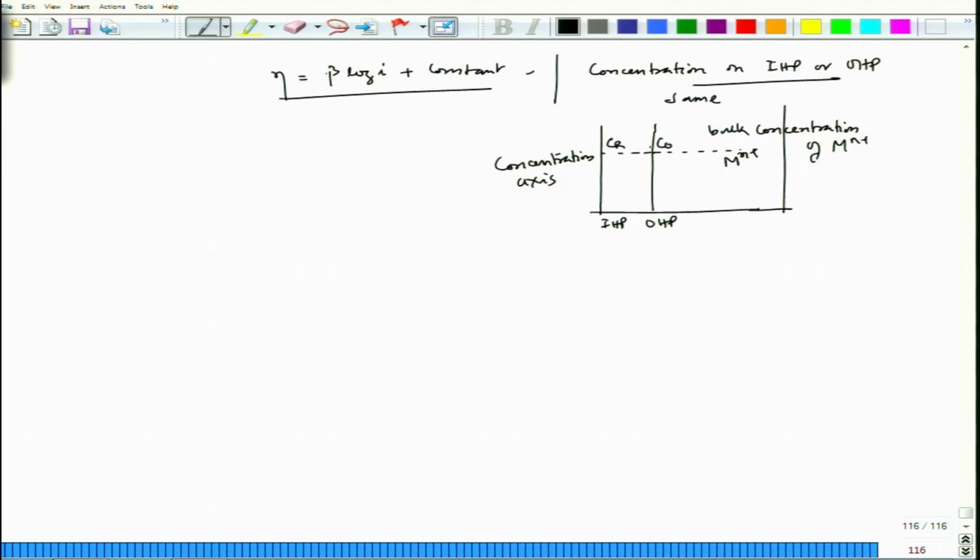Now, in fact, if I try to see this particular reaction, which is a cathodic reaction, in that case if we have this continuous cathodic reaction, there could be a possibility that metal ion is consumed heavily, so that there could be a depletion of metal ion at the interface, and the depletion is with regard to the bulk concentration of metal ion in that particular medium of the aqueous solution. So, that time we have a concentration difference. That concentration difference might lead to some polarization again. That polarization is called concentration polarization. We will talk about that part.